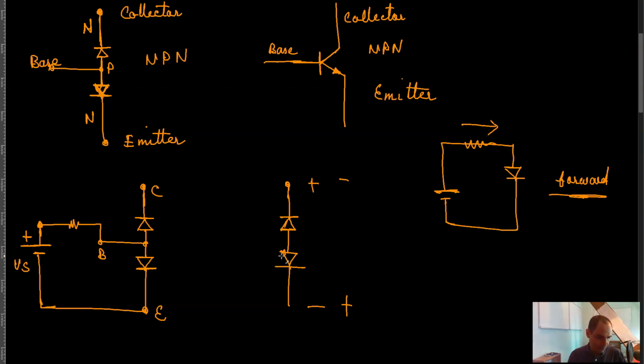But what happens in a BJT, when there is base current flowing through your transistor, is that this part between the two diodes, if you imagine you have NPN over here, so this is N material, this is P material and N material, and you can imagine that the P material is essentially very thin.